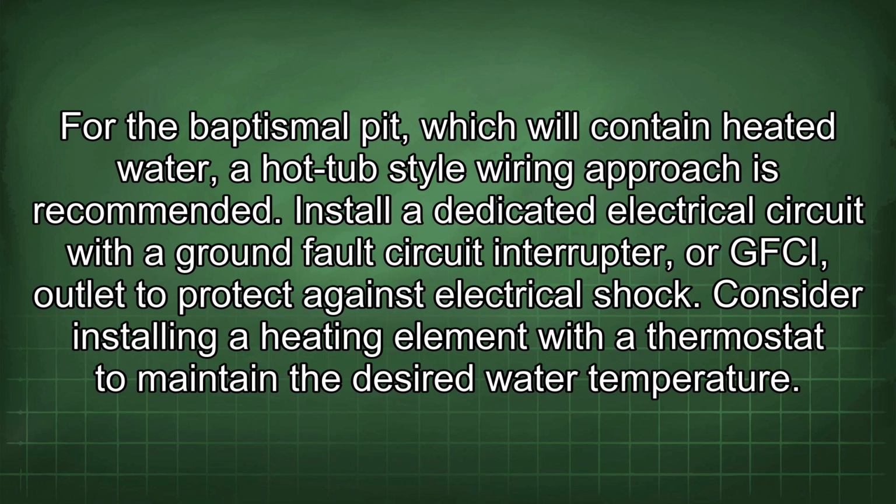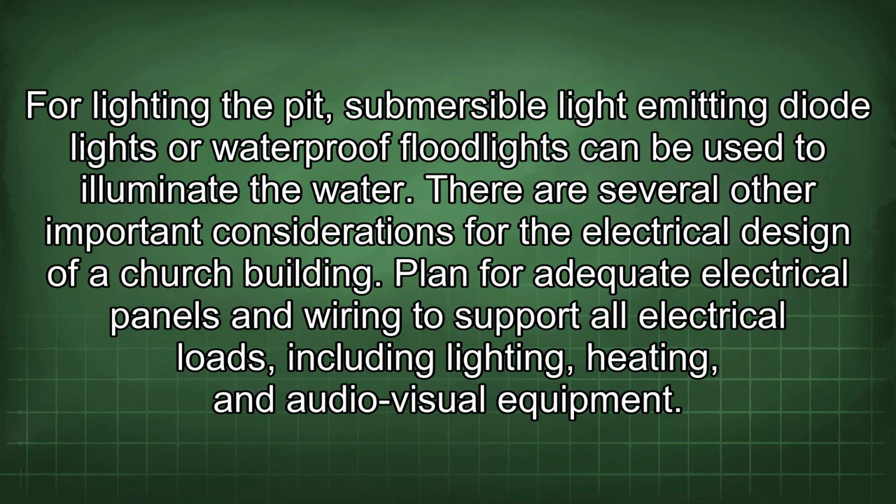For the baptismal pit, which will contain heated water, a hot tub-style wiring approach is recommended. Install a dedicated electrical circuit with the ground fault circuit interrupter or GFCI outlet to protect against electrical shock. Consider installing a heating element with a thermostat to maintain the desired water temperature. For lighting the pit, submersible light-emitting diode lights or waterproof floodlights can be used to illuminate the water.